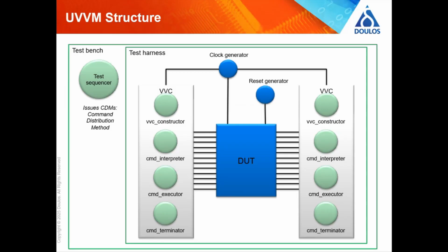And UVVM, similar idea, if anything more structured, because within our VHDL verification component, we've got separate ideas of a constructor, an interpreter which looks at what commands are about to be executed, an executor which actually does them, and a terminator which finishes them. It's quite a prescribed way of working in UVVM.